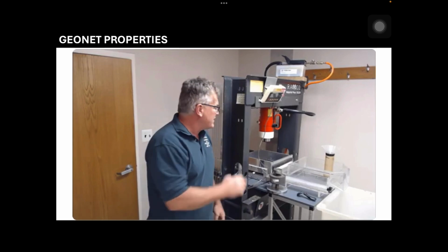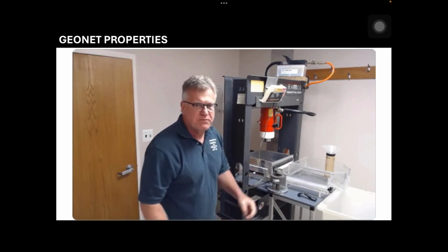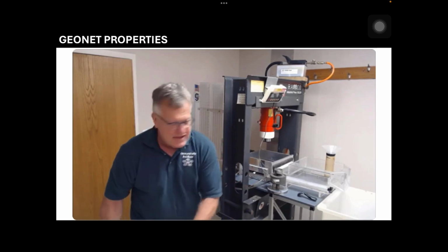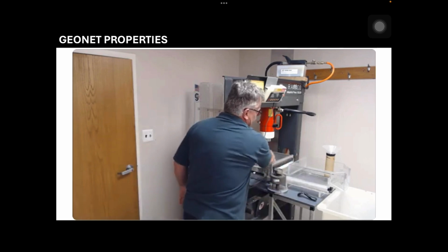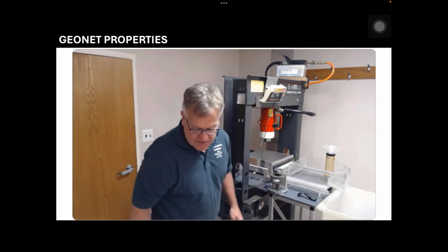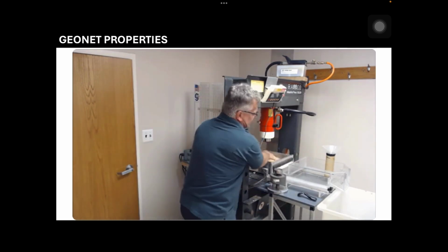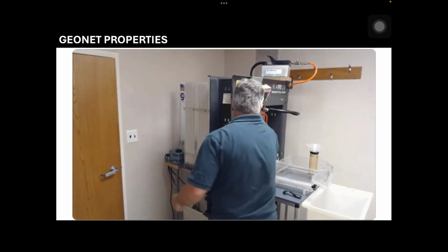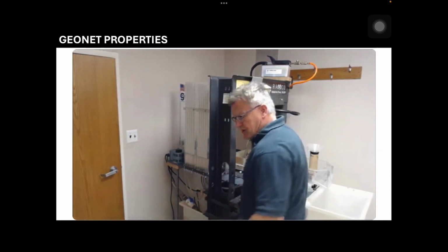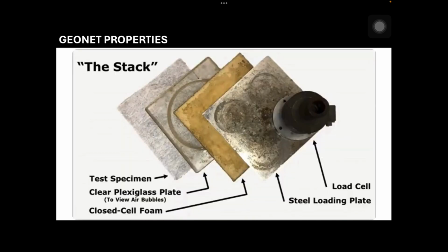Critically important not to have any air in the interstices of the spacer or the net, so therefore you place typically a plexiglass lid over top of it. Then you're going to need some sort of seal. We use a closed cell foam for this particular case, so that we don't have any leakage around the perimeter of the holder. And then a big pressure plate so that we can apply the normal pressure.